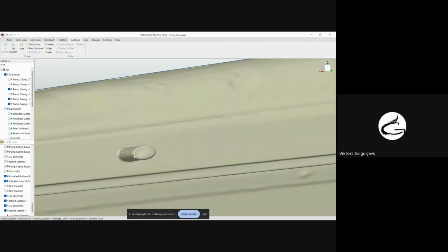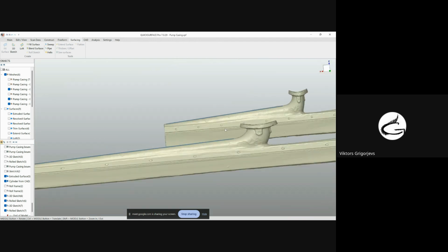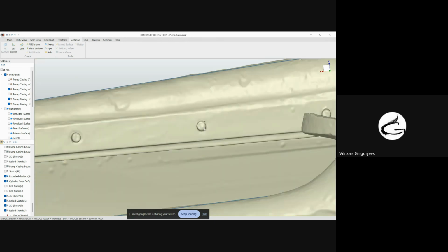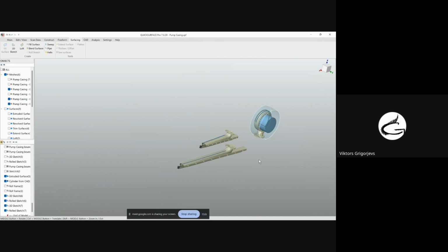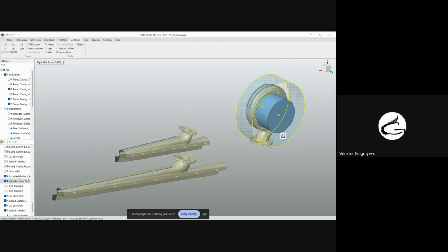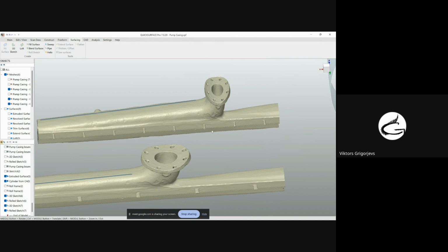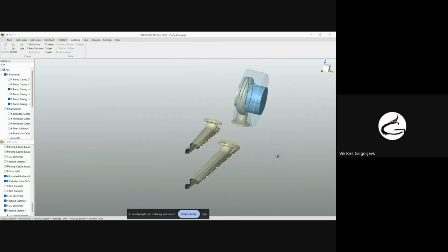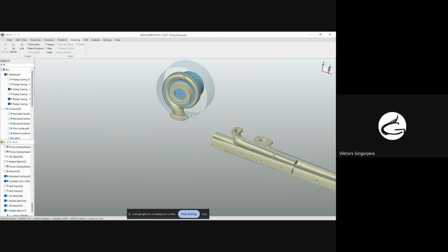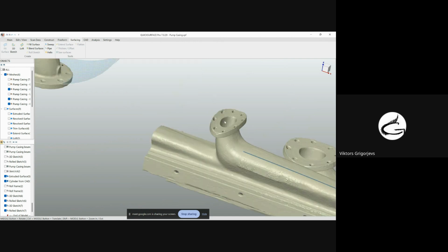So here we can see that our studs are oval studs, and here we can see that they are round ones. And considering that the larger diameter was pretty close to this flange, it looks way less distorted than this one. Exactly. So it basically depends on which part you want to work on, and to have a more exact representation of how it looks unrolled in real life, just not to let yourself be confused because of the shapes that you see here right now.